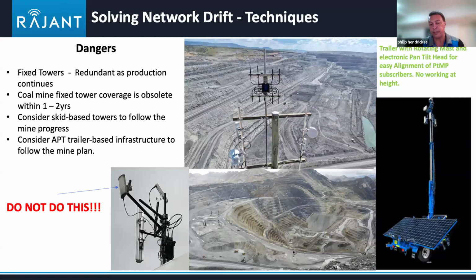So that is one of the things that we're going around and finding that guys are actually trying to do right now: they have these sector antennas and they're trying to focus the sector antennas all the way down to the pit. Yes, the RF coverage from that antenna is going to be better, but all you're going to do is increase the noise floor, and no one's actually going to be able to respond.